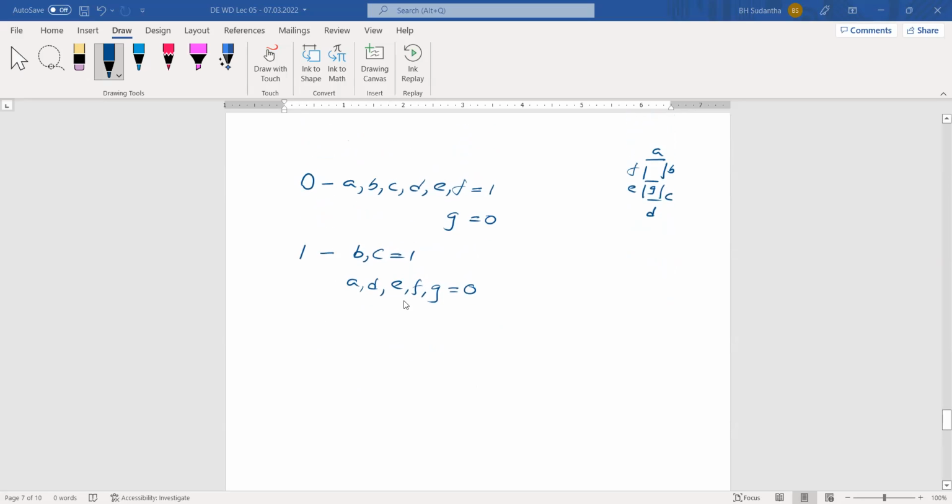Then in binary, we have several bit patterns here, and we can send these bit patterns. In our case, whatever circuit we made, if it is a number, then all numbers will be in binary format. But this 7-segment display cannot understand this binary format. Then we have to convert this binary format into a kind of code that this 7-segment display can understand.